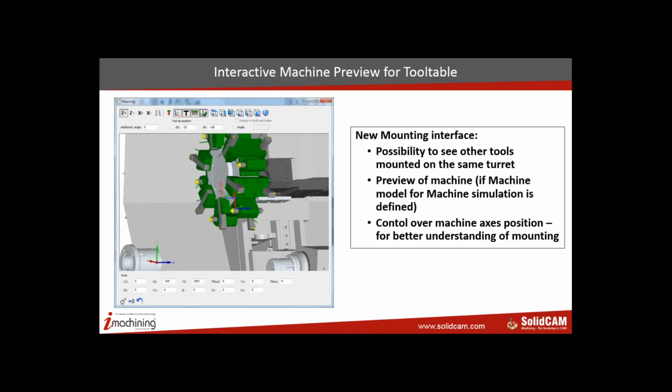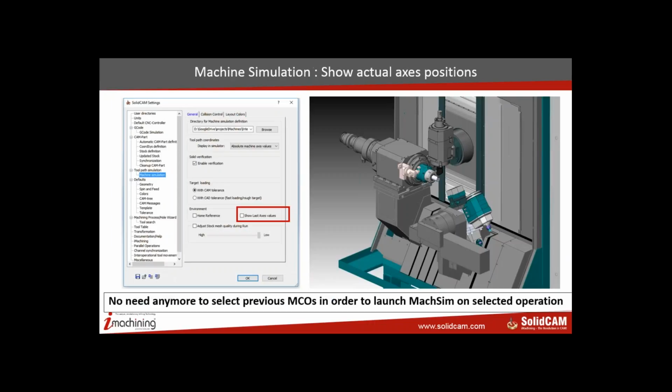Interactive machine preview for the tool table, as I mentioned earlier, so you can now see all your tools as they would appear on the carousel or on the turret of the machine, and you can see how they may need to be moved or changed if they're fouling each other, etc. A bit more easy to see. And in machine simulation, you can now actually show the actual axis positions all the time. No need to select previous MCOs in order to launch it.